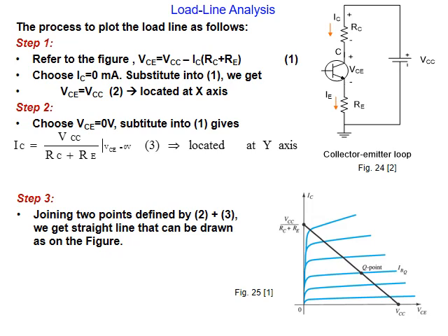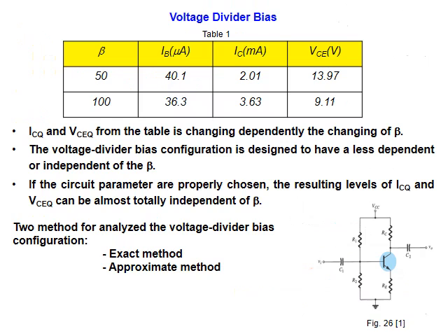Now, if we work using load line analysis, we can do the same. We can find also the operating point, and then we can go on to calculate V collector, V base, V emitter, all of them. Because from the load line analysis, we will find the quiescent point. It means VCE, rather than by calculation, we will find it from the graph, and IC. Definitely Q here. Okay? So the procedure is clear. We can apply it and also graphically find the unknowns of the circuit.